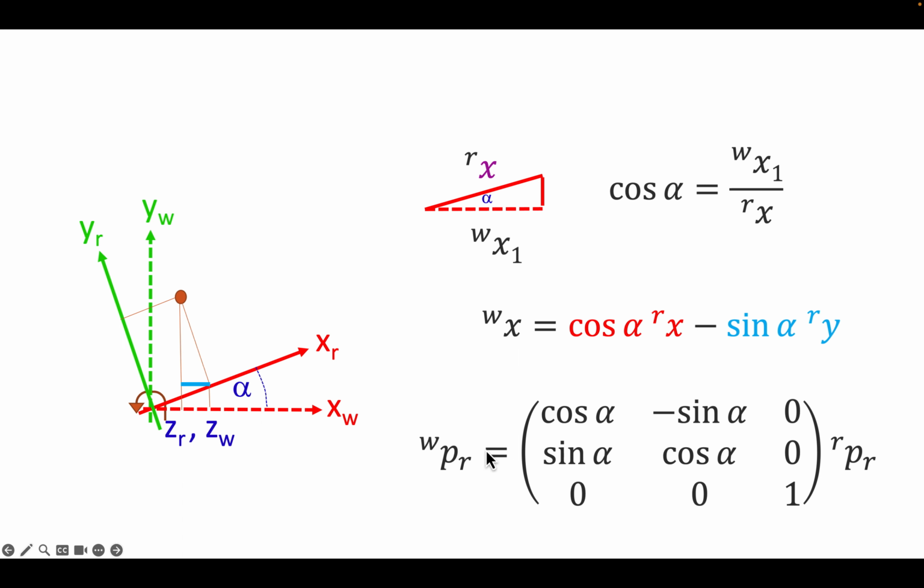I have the matrix now here. It has 3 components. The first line takes the x and the y from the robot coordinate system. Now, in order to get the second row, I can do very similar operations. I'm looking for the point where this point intersects the y coordinate of the world frame, and I can apply very similar reasoning, adding this time 2 components together to get the point on the y-axis.